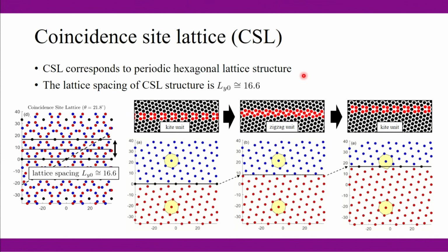Okay, right. So here is just an example. If we are forcing the grain boundary in a different vertical direction, what we are seeing here is exactly the coincidence site that is marked in black here, right? If you go over some periodicity, you are once again seeing the black site occurring here. The difference here and here is the same because we are using periodic boundary conditions. So the kite structure always corresponds to the line that goes across the coincident site lattice.